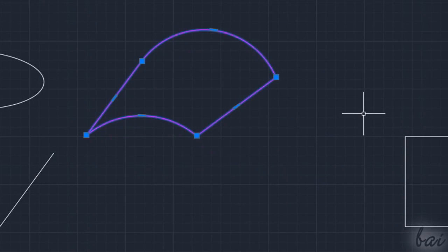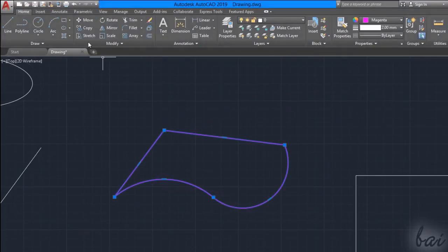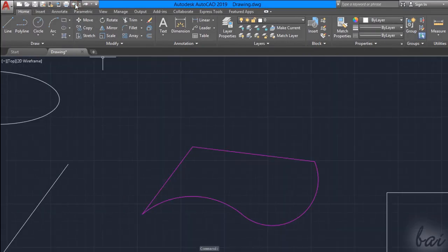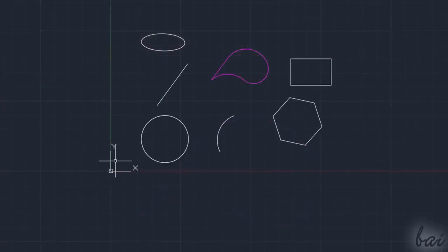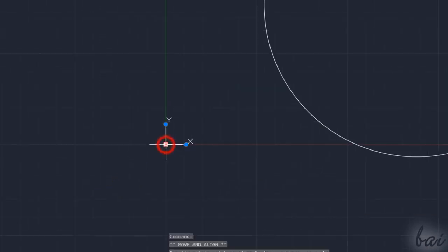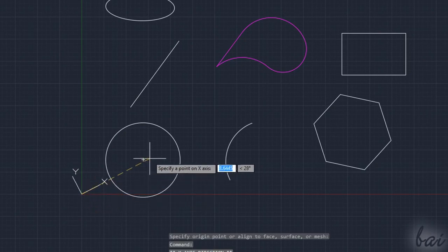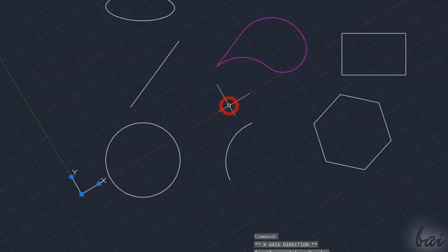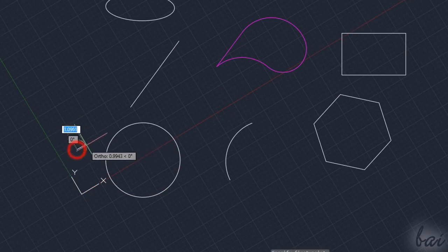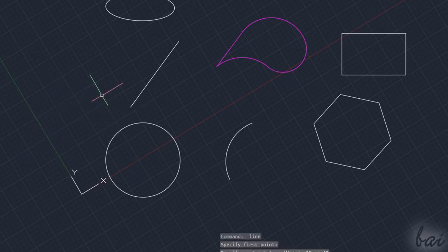In case you make any mistake, remember to use Ctrl and Z or the Undo button to reverse your latest actions made. The gizmo system seen before is indeed an object with blue nodes if selected. Use the square node to move its origin, and the blue circles to rotate the system as much as its X and Y axis. Consider that this changes the reference for the horizontal and the vertical directions, represented in red and in green colors on the workspace.